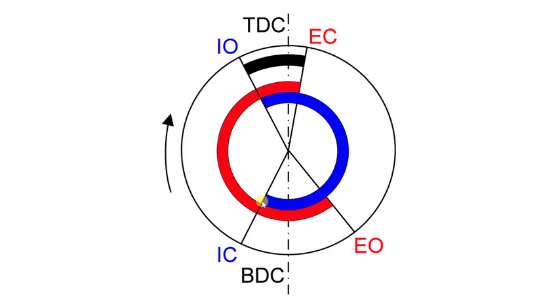Where we're drawing fresh air in and the exhaust valves are open, that's effectively the scavenging period where we try to get the exhaust gas out and the fresh air in. Then we close the exhaust valve here and allow the air to be sucked in as the piston goes downwards, and then we get our compression stroke again.